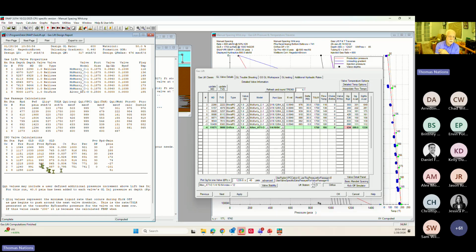The other things here important for gas lift design are this is the temperature correction factor that's used to correct the bellows pressure, the inside-the-bellows pressure, from downhole temperature to shop conditions. PIO, pressure injection opening. That's at surface. So this describes what the opening pressure at each gas lift valve would be if the flowing tubing pressure were equal to this, to the transfer pressure.